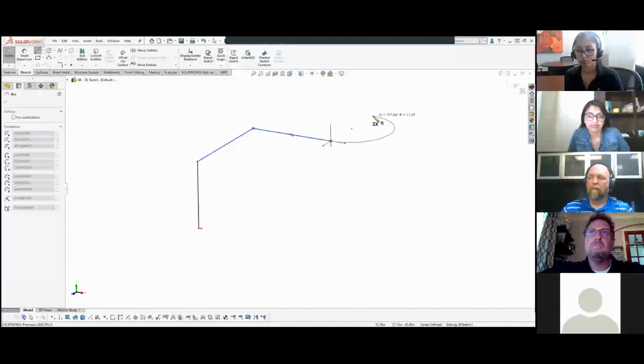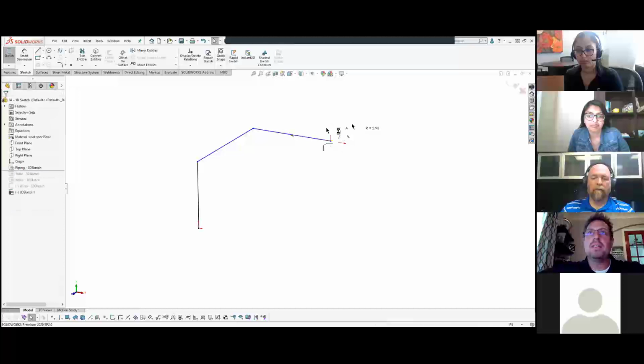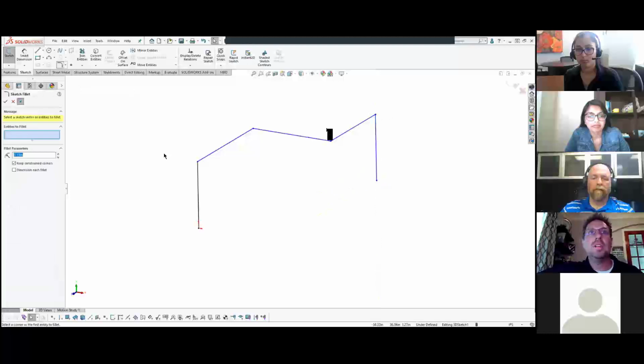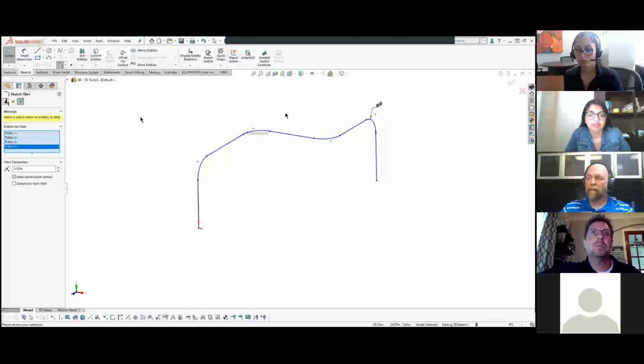Let's go back again. Oop, you can see I can do the same thing that Tim did with the arc. I'm actually going to go back in the line command. And tab it. And let's go over, and then I'm just going to go down just a little bit more. And we do have fillets, so I can create fillets. It's a pretty good size, so I'm going to make little 5-inch fillets on there. And again, this is going in X, Y, and Z all at the same time.